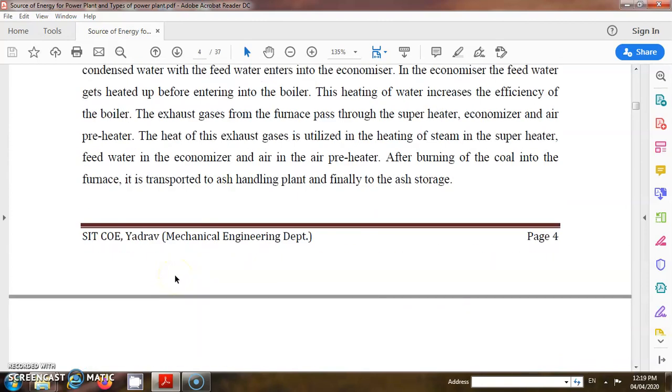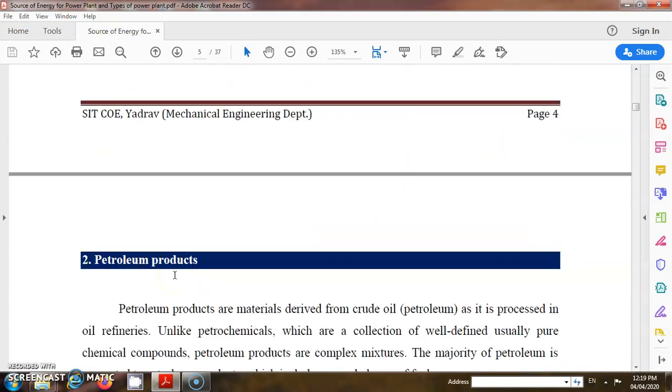The steam power plant works on the Rankine cycle. There are four processes in the PV and TS diagrams. The first is the heat addition process, which occurs in the boiler. The second is the expansion process, which occurs in the turbine. The third is heat rejection, which occurs in the steam condenser. And the fourth is the pumping operation, which happens in the pump.